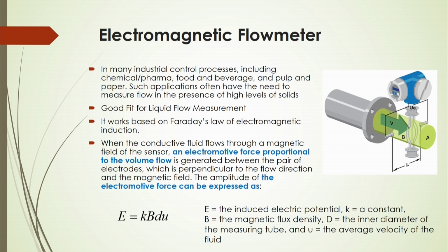Now, in this case it works based on Faraday's law of electromagnetic induction. Whenever a conductive fluid flows through the magnetic field of the sensor, an electromotive force is generated, and that electromotive force is proportional to the volumetric flow rate of the fluid. This electromotive force is generated between the pair of electrodes, as shown in the figure.